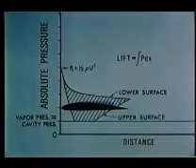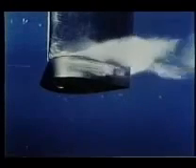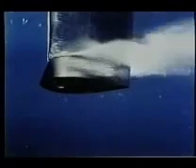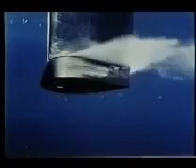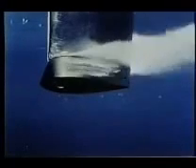Actually, as cavitation develops, the shape of the pressure distribution changes somewhat. The resultant pressure distribution is such as to cause an increase in drag. Thus, hydrofoils, and for the same reasons, many hydraulic machines which are designed for efficient subcavitating operation lose efficiency when cavitating.